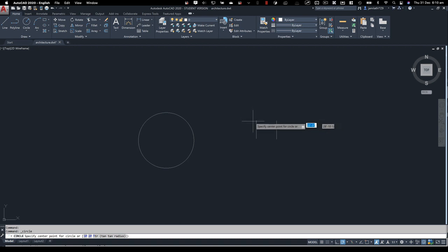Now another thing you notice here, what if I want to actually select the end point of this line? Right now, I'm not able to do that unless I specify the exact coordinates for that endpoint, or I can turn on something called snapping. Here we got this snap cursor to 2D reference point. I'm going to just turn it on.